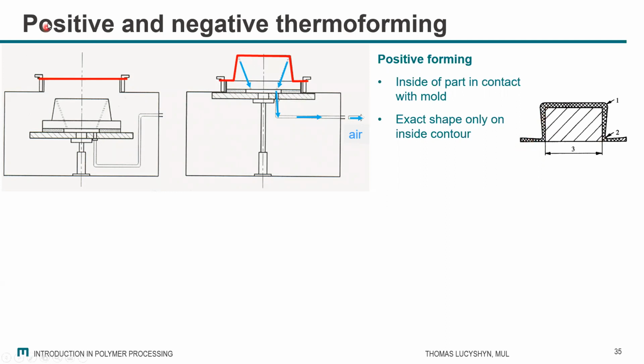and that would be the part that would be stretched last. So just imagine you're starting to stretch the material over this mold, then this part would be the last which is deformed and has quite a large deformation, and therefore it's stretched a lot, and therefore the material becomes thinner in these regions.